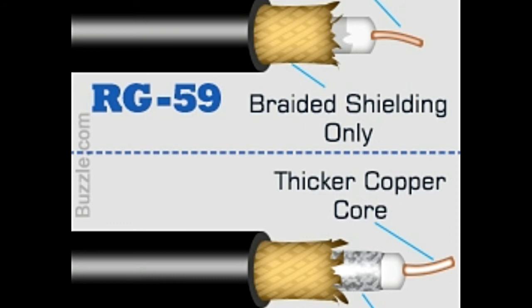In cases where transmissions are needed for long distances or signal frequencies of up to 1.5 GHz, RG6 cables are the best. Thus, they are ideal for TV antennas, satellite transmissions, and high-speed internet broadband. Also, RG6 cables have thicker and more durable jackets, which make them more suitable as compared to RG59 cables for outdoor use. RG6 versus RG59 coaxial cable performance.